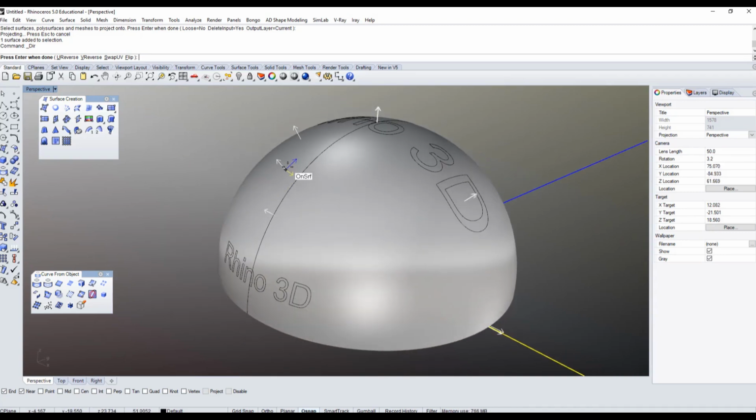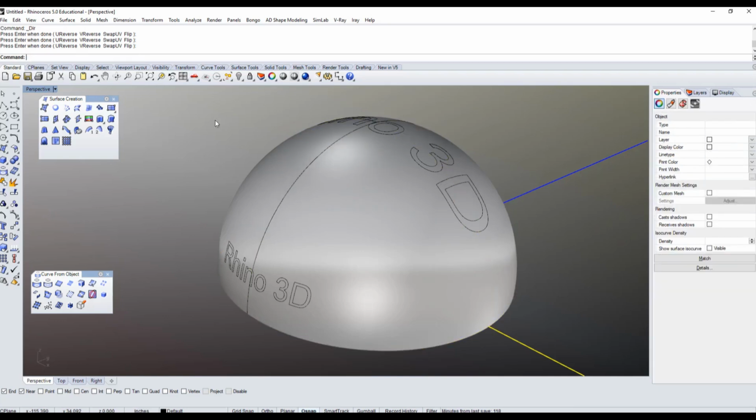Because if I was to left click like this, and I invert my normals, there are some functions that would give me a different result in the way the tools used would operate on my surfaces. So make sure it's a good habit to check sometimes, when you execute certain operations, that your normals are pointing outside. That is the convention, okay? So let me undo.